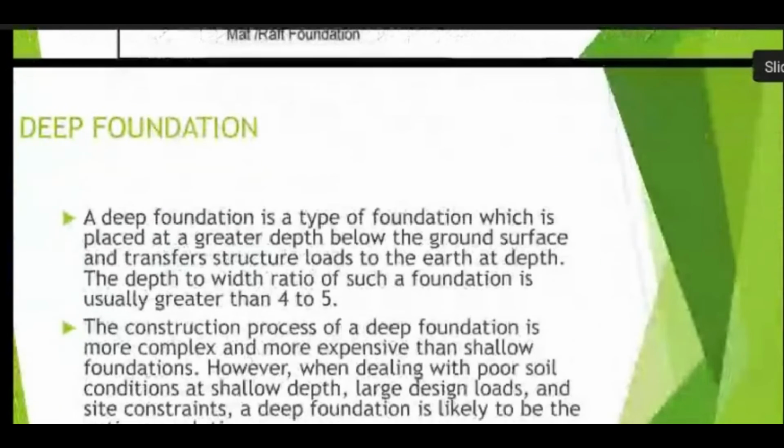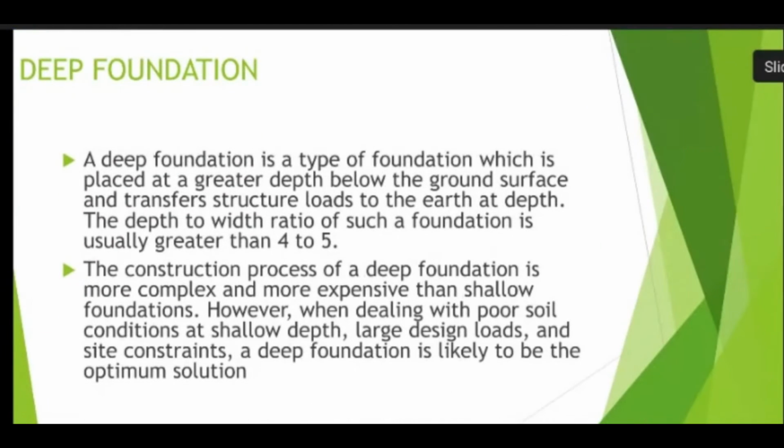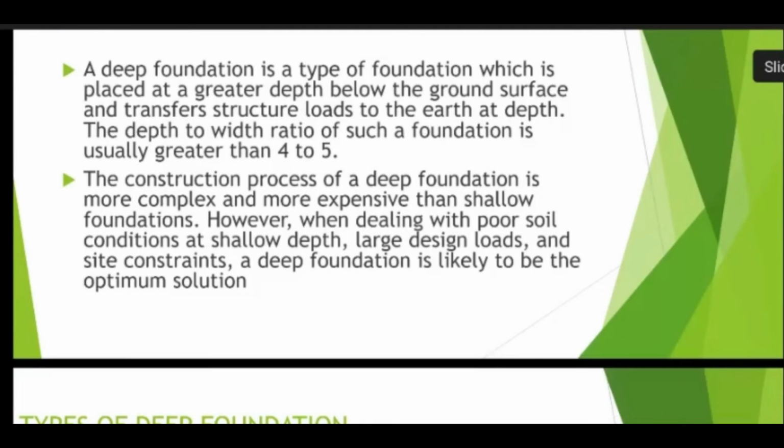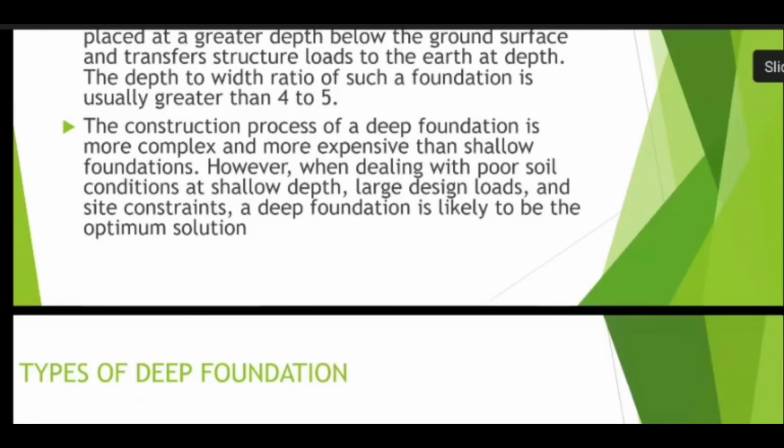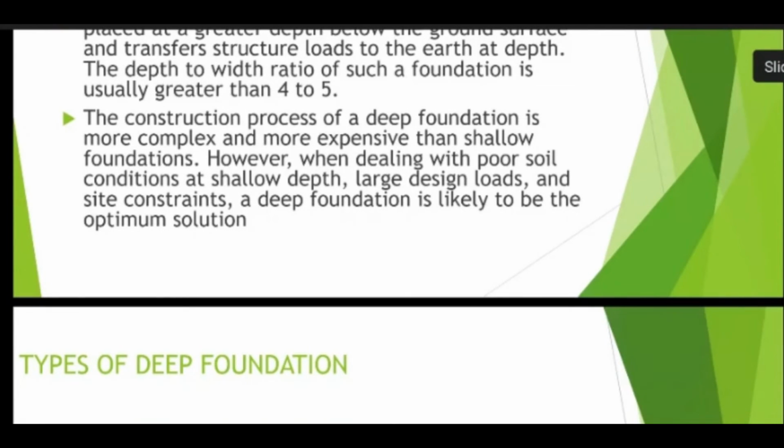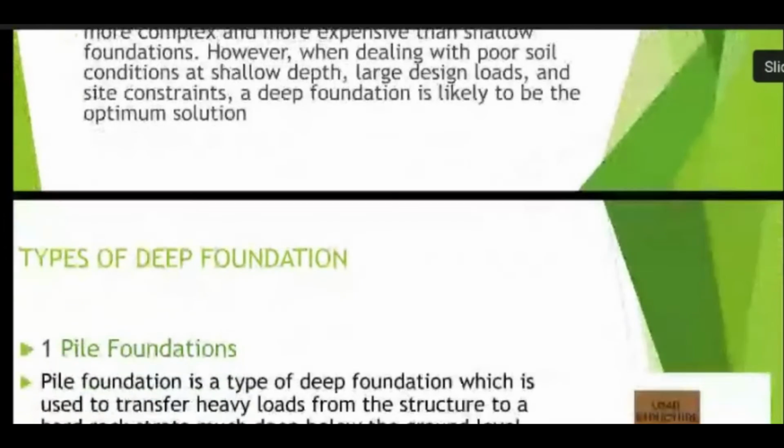Deep foundation. A deep foundation is a type of foundation which is placed at a greater depth below the ground surface and transfers structural loads to the earth at depth. The depth to width ratio of such a foundation is usually greater than 4 to 5. The construction process of a deep foundation is more complex and more expensive than shallow foundation. However, when dealing with poor soil conditions at shallow depth, large design loads and site constraints, a deep foundation is likely to be the optimum solution.